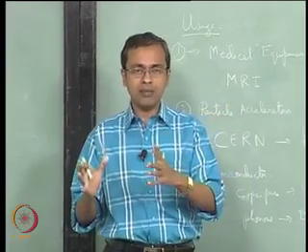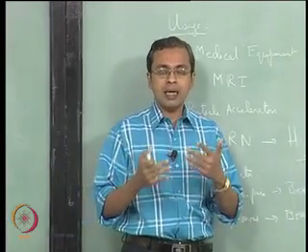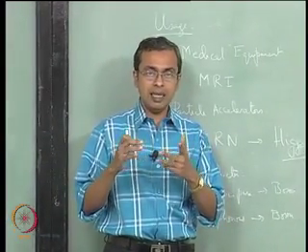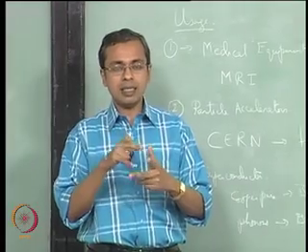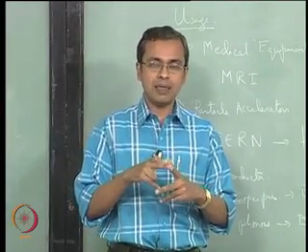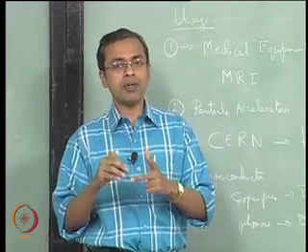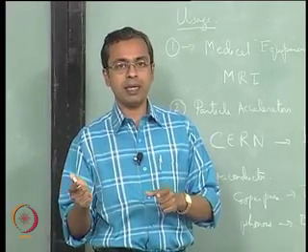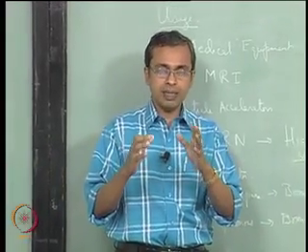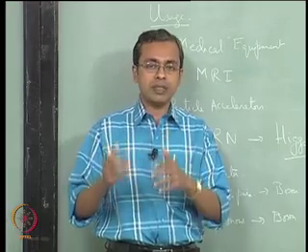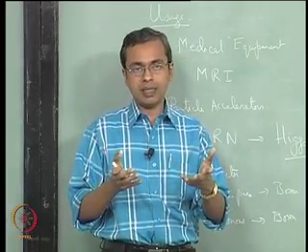For every given superconducting material, you can identify these three parameters: the H sub c, the J sub c, and the T sub c, and that will then give you the envelope within which you have to operate to keep it in the superconducting state. Okay, so this is the fundamental aspect of a superconductor. As I mentioned, of the three, more than the temperature and the current, it is the effect of the magnetic field on the superconducting behavior that formed the basis of trying to come up with a theory for understanding superconductivity.